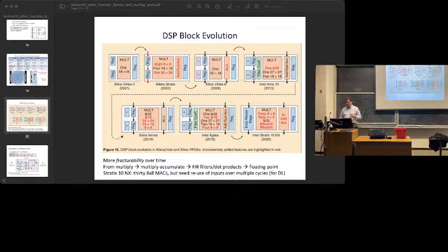So Arria 10 was the first FPGA that just said, we give up, we put floating point units in. And it wasn't clear at first whether that was a good idea or not, but in subsequent years, other chips have followed in its footsteps, so it's become kind of clear, no, that really is the right thing to do. And it is interesting because in theory, you don't need it. You could just get by, but it's too hard to get people to design all their systems that way. Lots and lots of FPGA systems still use fixed point. It's probably still dominant, so I'm not saying that people don't use fixed point.